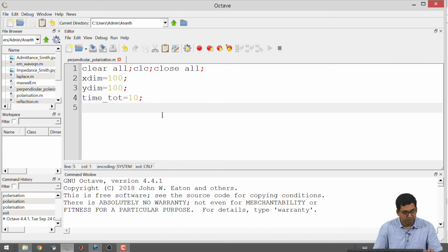Okay. So, in order to solve the 2 curl equations, there is one additional thing that you will need. You will need to define the position of a source of this electromagnetic wave, all right. In the case of transmission line, we would have used voltage at a specific place was equal to 1 or 2, etc. In the case of this 1D propagation, we would have used a source of electric field at a particular position. Need to have a source.